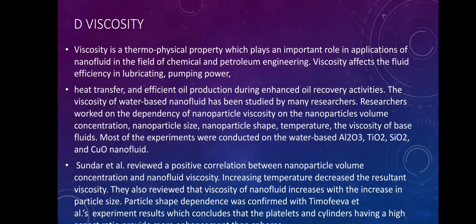Viscosity. Viscosity is a thermophysical property which plays an important role in the application of nanofluids in the field of chemical and petroleum engineering. Viscosity affects the fluid efficiency in lubricating, pumping power, heat transfer and efficient oil production during enhanced oil recovery activities. The viscosity of water-based nanofluid has been studied by many researchers.